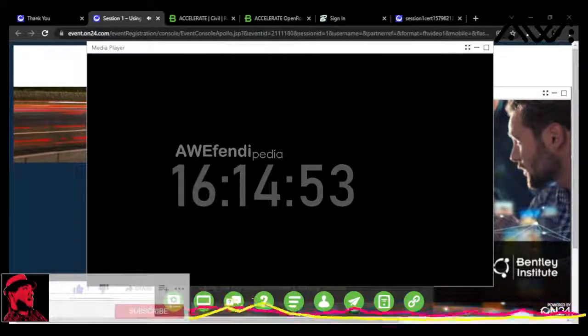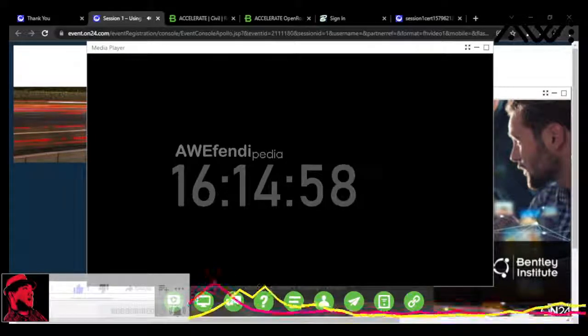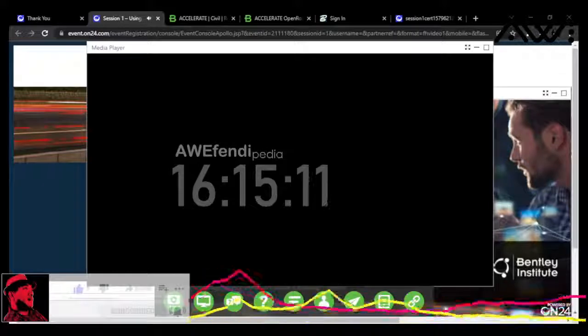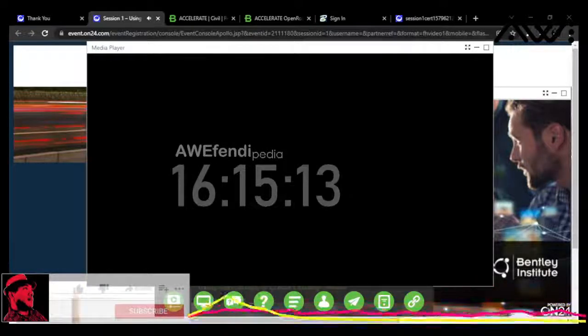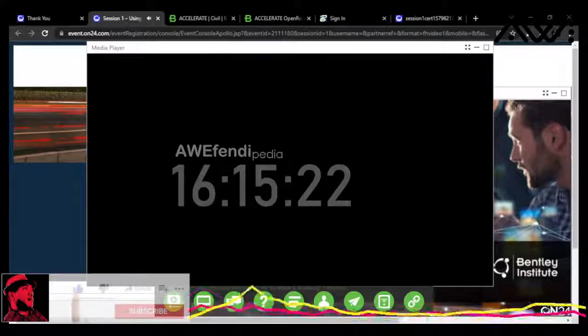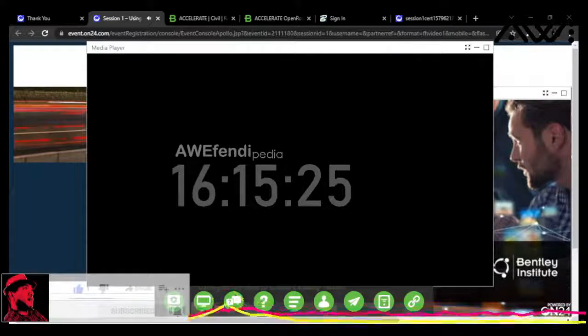So I'm going to do the same thing on the other side of our little driveway here where it starts. I'm going to click on the point, go to properties. I'm going to make this DW8 and hit enter on my keyboard. That's going to start the DW8 and then connect all other DW8s in the field book after it. There are none until I edit this one. And I'm going to make this a DW8 as well. Okay, so I have created 2 new strings, a DW7 and a DW8 for this one.